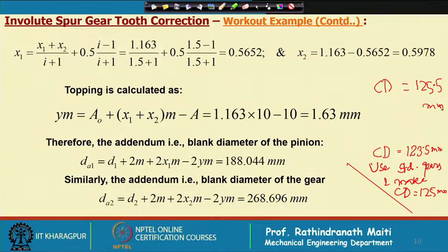In that case, there are two possibilities, that the minus correction is given to either of that or both of that, so that center distance can be made 125, plus the correction is such that there will be certain amount of backlash, or make it 130 millimeter with some positive corrections, mainly to the pinion and maybe a little bit to the gears also, so that the center distance increases, working pressure angle also will increase, but as well as there will be some backlash.